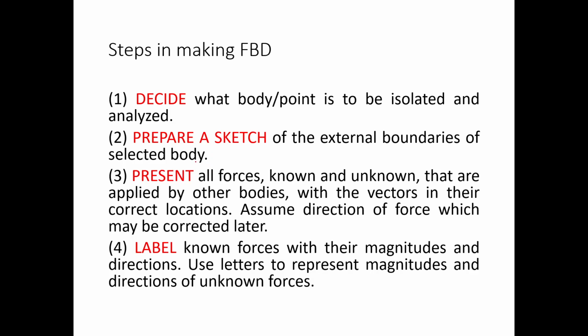So meaning you need to observe the forces that will act on that particular point or body. And the next is you present all the forces. So present all the forces, known or unknown, and also the external forces that are acting on that particular body. And then lastly, label your known forces with their magnitudes and their directions. You can use letters to represent magnitudes and directions of unknown forces.